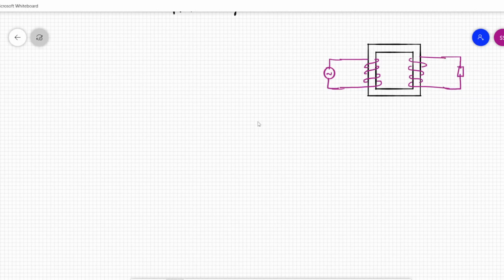Now I am going to give a single phase AC supply of 50 Hz generally. So a voltage V1 is applied. E1 will be induced in the primary coil, and there will be a flux production first. This flux will link with the secondary coil also. This flux linkage will induce some EMF E2, and this will cause some current I2 to flow when it is a closed circuit, and V2 is the voltage across the load terminal. Right, this is what we have seen till now. There is a current flowing in the primary, that is called I1. So I1 is the current in the primary winding.